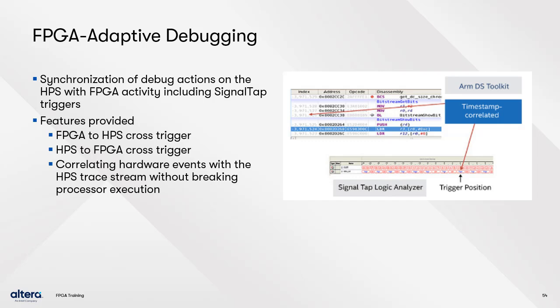Finally, you can correlate hardware events with the HPS trace stream without breaking processor execution through events. FPGA to HPS cross-trigger and HPS to FPGA cross-trigger are supported.